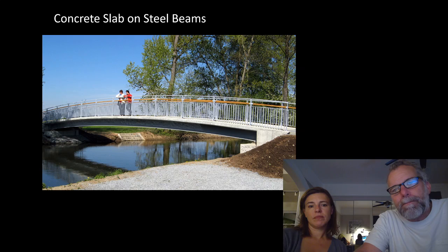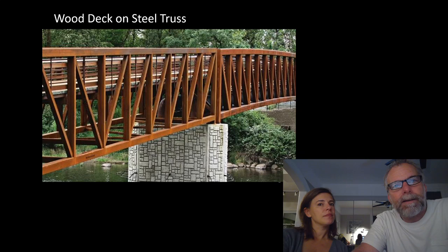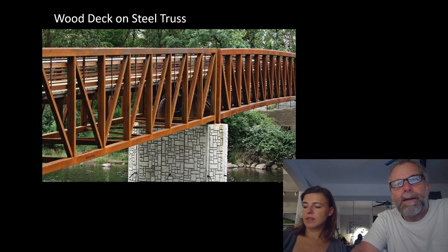So this is an example of steel girders with a concrete slab as the deck, which adds mass, reduces the perception of vibration. This is a very common type of pedestrian bridge. It would be a wood deck with steel trusses. The Eagle Bridge in Canada make these. Lots of people make them, but Eagle Bridges are ubiquitous. That rusty steel basic form look is who you've seen. Yeah. Corten is extremely common for bridges because it's long life without protection, without relying on coatings.